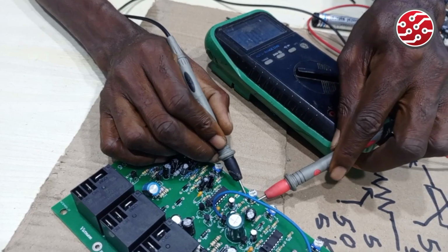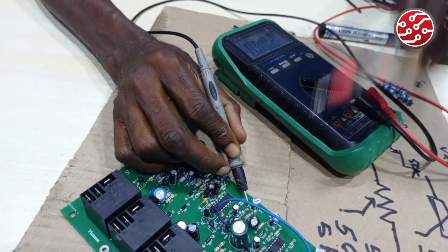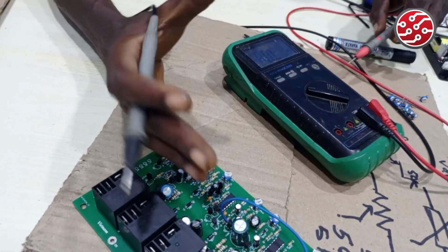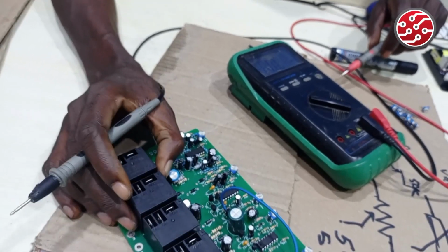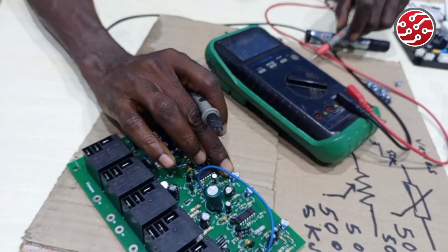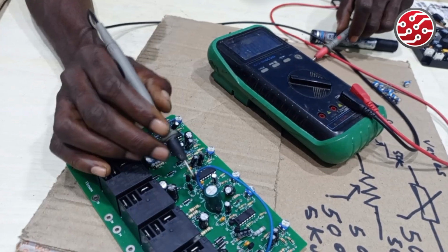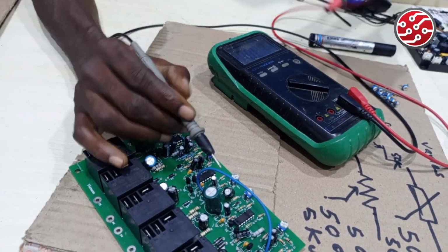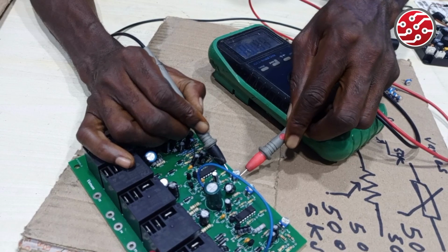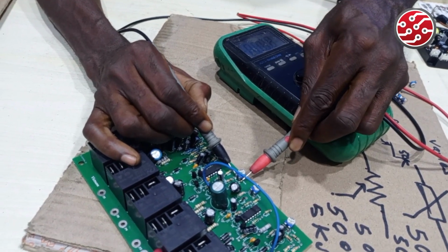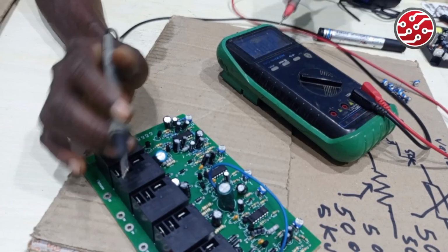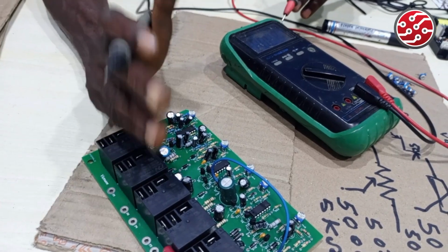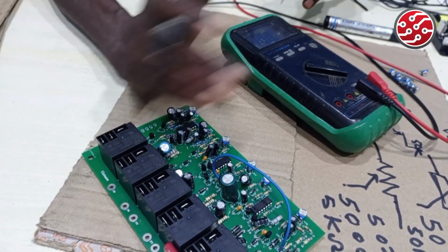But when you read it like this and it gives you more than the rated value, meaning that variable resistor is bad. So if you're a technician, don't just go and be varying this variable resistor the way you like and changing it the way you like. Work with precision. Read it. If the resistance is out of range, you know that is bad. But if it's not out of range, you know that is good. That's one of the ways we read a variable resistor and know if it is bad or good.